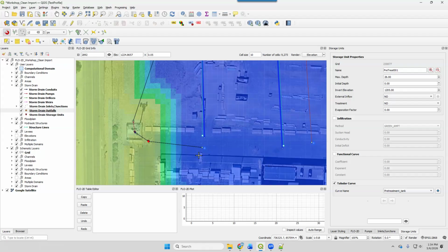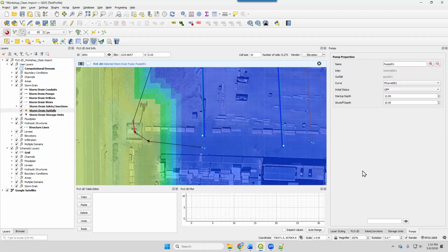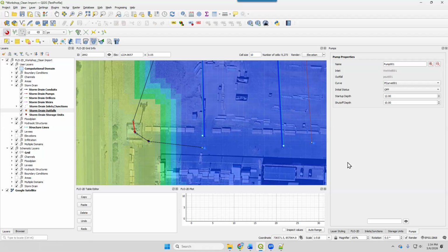All right. And then moving on to the wet well for the pump. Same thing. I went online and found the pump design specifications and based the sizing of the wet well on the flow through this pump system. In this case, I think we're doing something like 10 CFS. Actually, you can set up 3 pumps here, have 2 of them on and 1 of them off, and you can configure this with 3 pumps connected to these nodes. And I think that's okay, but I just did it using 1.